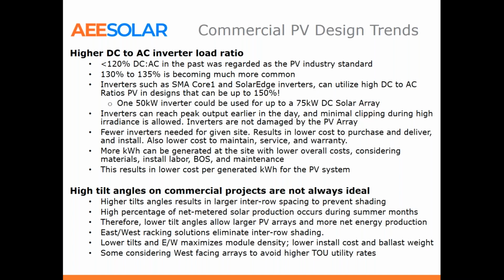So it results in much lower cost per generated kilowatt hour over the lifetime of the system. Also, people just getting into commercial projects, there's a tendency to try, on flat roofs and sometimes on ground mounts, to have those higher tilts, thinking you have to tilt at latitude, have to get these things tilted up.